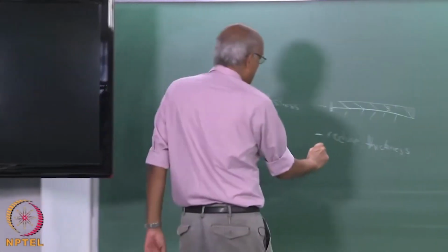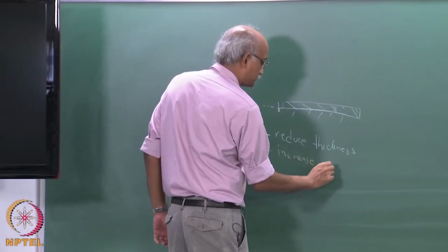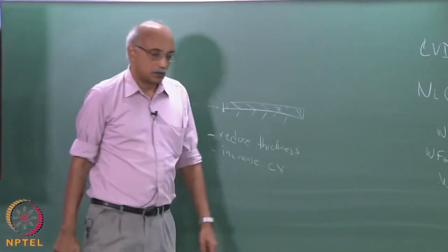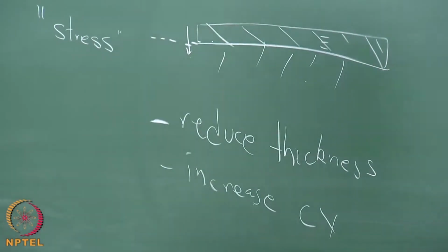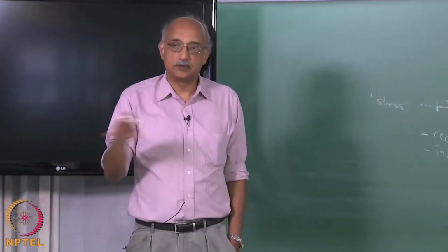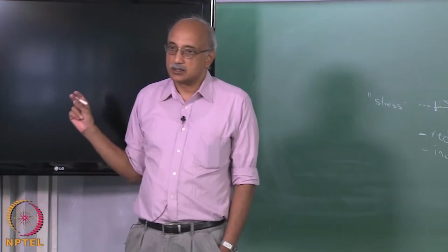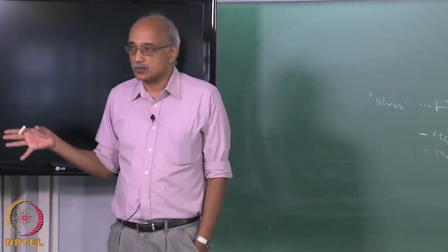The second is to increase the radius of curvature. Even though CVD is much better than other coating processes in terms of being able to follow the contours of a body, a smoother or more curved surface is easier to coat than one that has very sharp transition points.